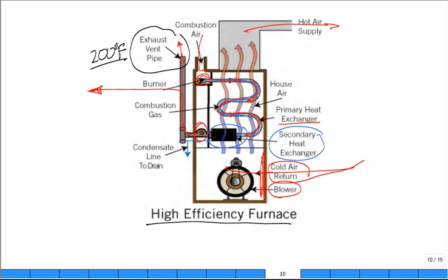But you have to have some mechanism to collect up the condensate. And what do you do? You typically dump it off to a drain in the basement. And the drain could sit in there and then evaporate, or it could have a sump pump and throw it out after a while.